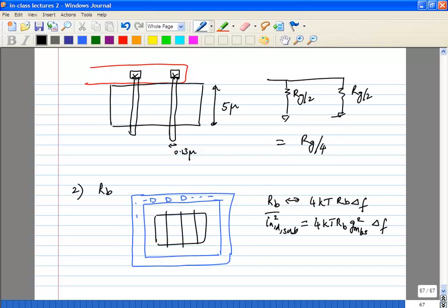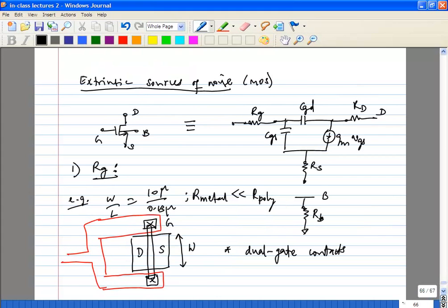Do you have any questions on LNAs? We are going to move on to mixers. Any other questions for your project? How do we get this last noise current expression? The voltage noise from the RB is 4kT RB delta F, and that is at the bulk node. That is converted to the output, and you actually have a gmbs here in parallel with gm.